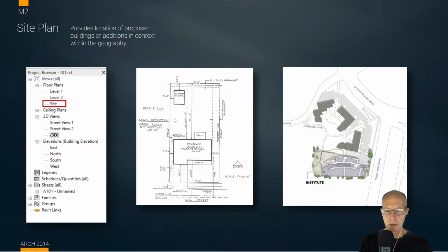This is also a site plan, but it's a site plan for the location of a home or residence on a site, and it indicates the distances from the lot lines around. And this would be used in the filing of a building permit. So the one on the left is for, let's say, filing for a building permit, and the one on the right is maybe to make a community presentation about why we're locating the building in the campus the way we are.